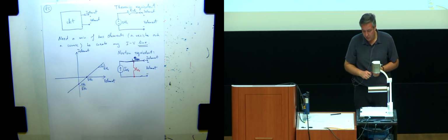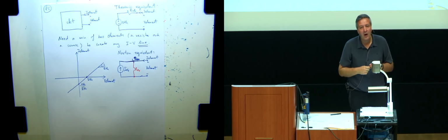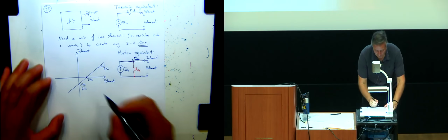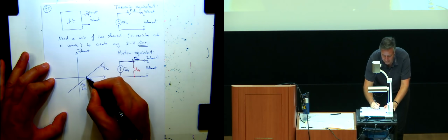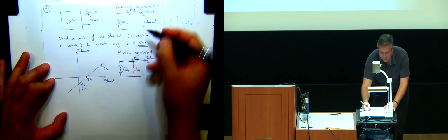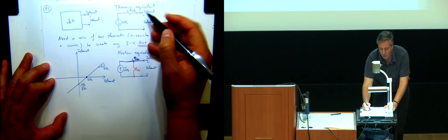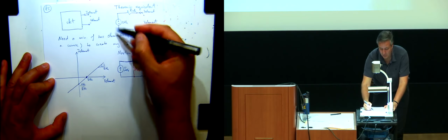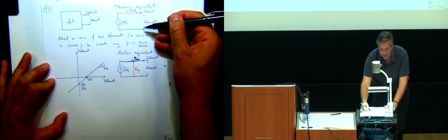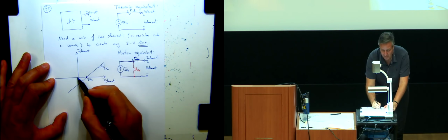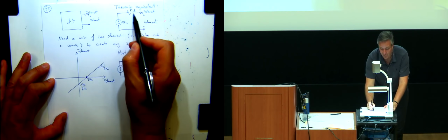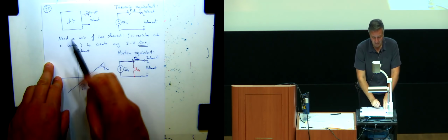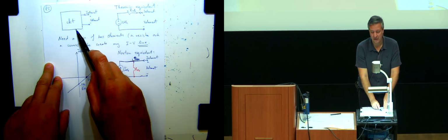However, this actually tells us how we find these values. If I look at this IV curve, we just said that I can find V Thevenin as the output of the circuit when I element is 0. Just looking at this circuit, V element is equal to V Thevenin when I element is 0. That means there's no voltage drop on R Thevenin. So the same thing has to be equivalent for my circuit.